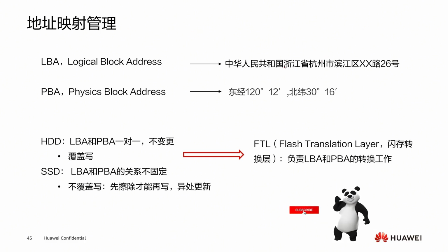That is the configuration of the host inside the SSD. The SSD master control and flash are accessed through the flash configuration as the basic unit, called a physical page. Every time the host writes a host configuration, the SSD master control will find a physical page and write the host's data. The SSD internally also keeps such a mapping relationship. Next time the host needs to read a certain host configuration, the SSD knows from which position on the flash to read the data.